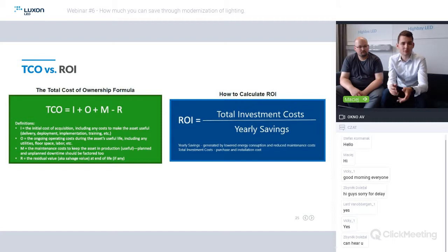Once a year we check the lumens, the luxes on the floor. We check if everything is correct. We clean and wipe the luminaires so they can operate 100% without any dust that they got throughout the year of usage. One yearly servicing is the minimum we implement within our offer for end customers.